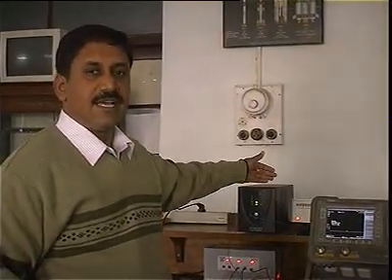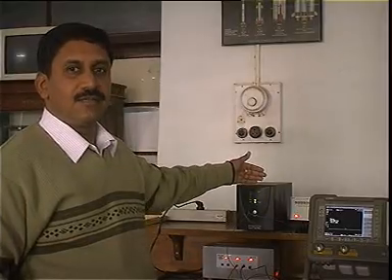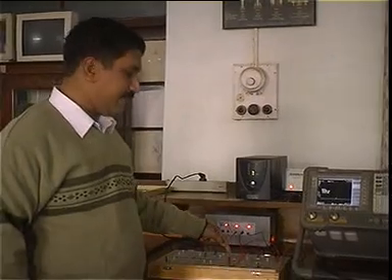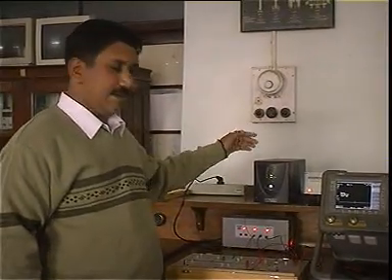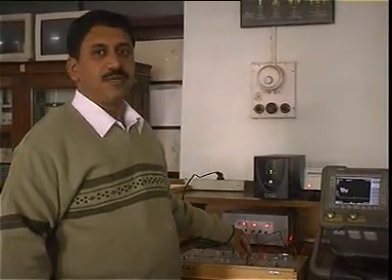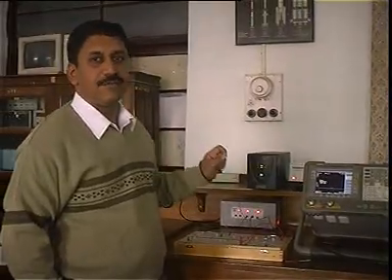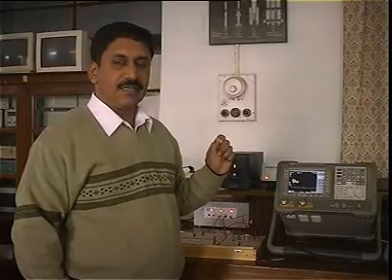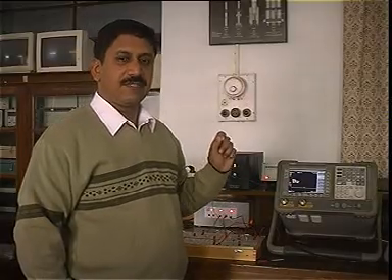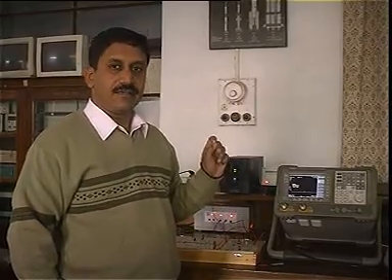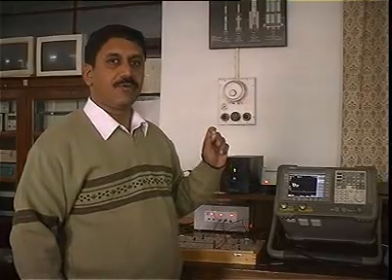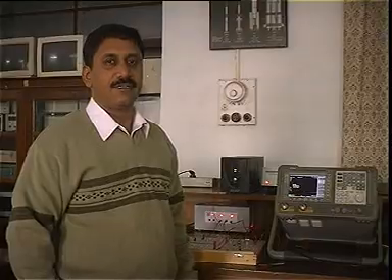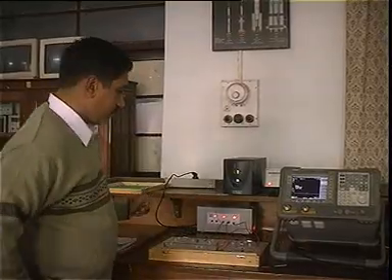The sine wave is set at 20 kilohertz. So frequency of the sine wave is 20 kilohertz. Now this sine wave, which is the modulating signal, will be input into this VCO. The VCO will produce a frequency modulated output. Now the frequency of the carrier is varied in proportion to the message signal. That is, the oscillator frequency changes in proportion to the message signal. So in effect, you are generating frequency modulated signal. We will just demonstrate the concept.